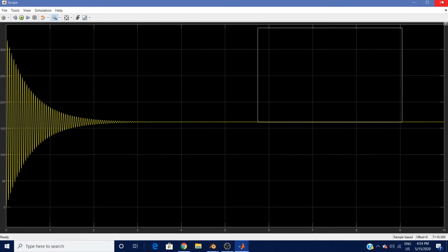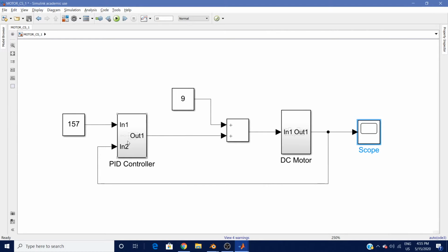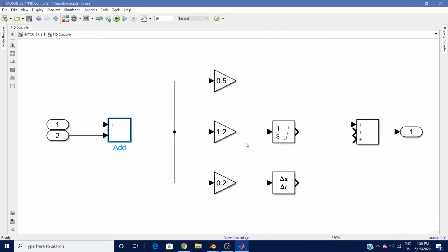Okay, so let's get out of that. So that was just the P controller. If we added in the integral component, we have some value of Ki. Now this Kp, Ki, and Kd, these values, you just tune them. You keep changing them till you find something that you like. For most cases, of course, you can formally figure out what they should be, but in this case, we've just arbitrarily taken values that gave us output similar to what we wanted.